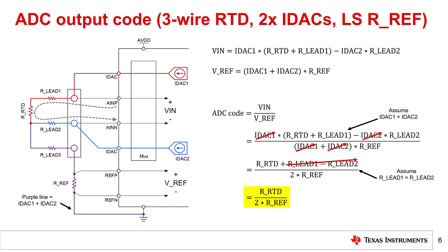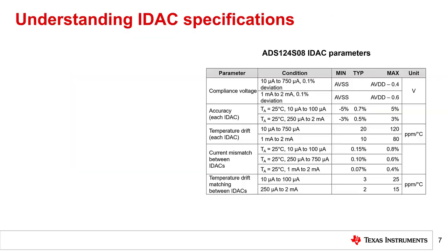Before moving on to analyzing a circuit with a high-side RREF, however, let's first consider the two assumptions made on this slide. While we have previously justified assuming the lead resistances are equal, we have not validated the assumption that the IDAC output currents are equal. Therefore, let's delve into the specifications for the IDACs integrated into the ADC to understand how practical this assumption is.